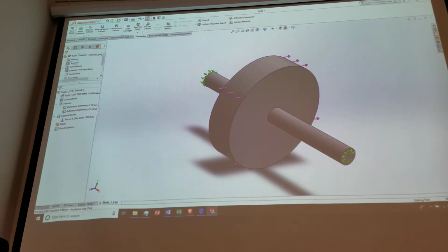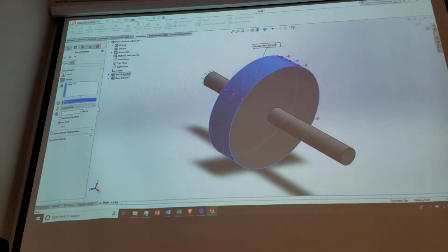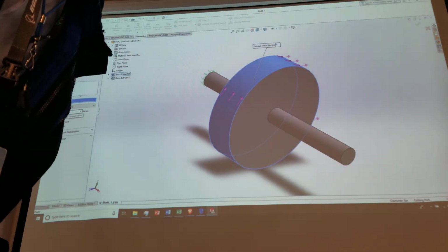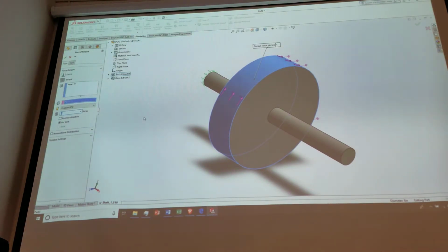And then I can put a torque on it here. The same thing, we'll put a torque on this guy here, that same force over there, right? My reference geometry, I can actually use the same surface for. How did you get the force to do what it's doing? You select the direction. You don't want it normal to surface, you want to select the direction. And then you have to go pick a reference for it. So in the one underneath, I picked the front plane. Okay?